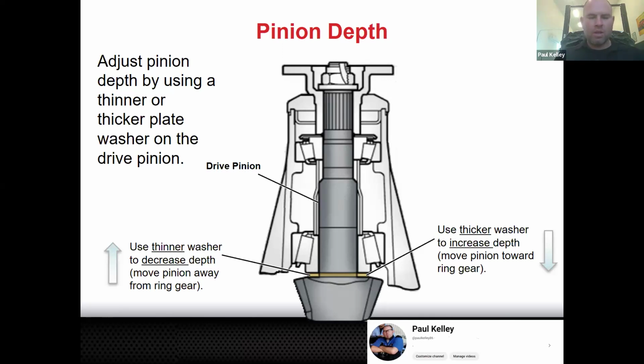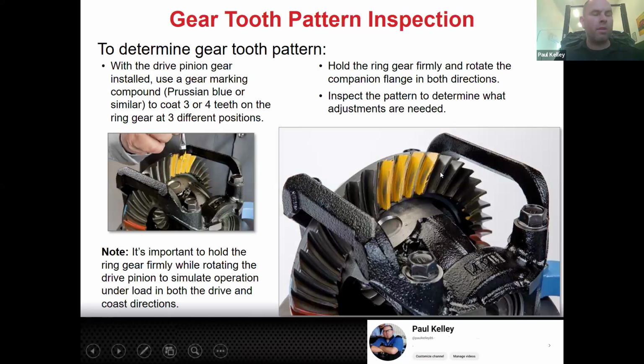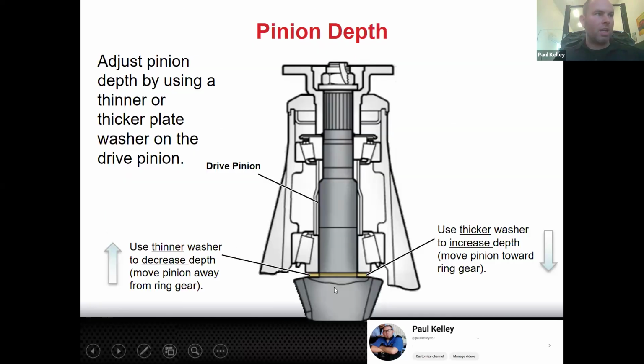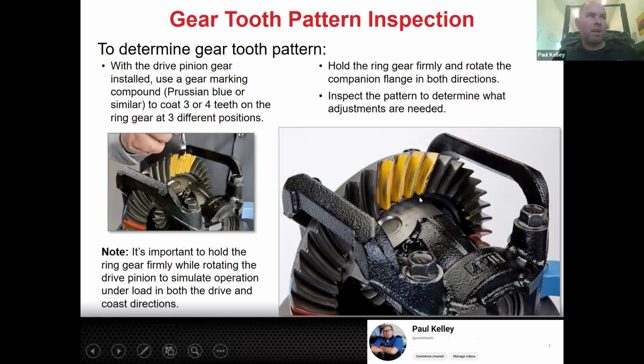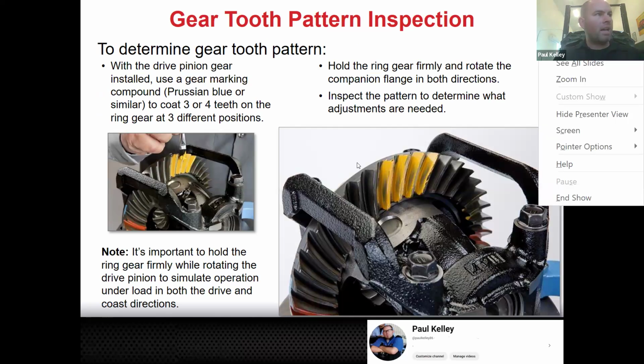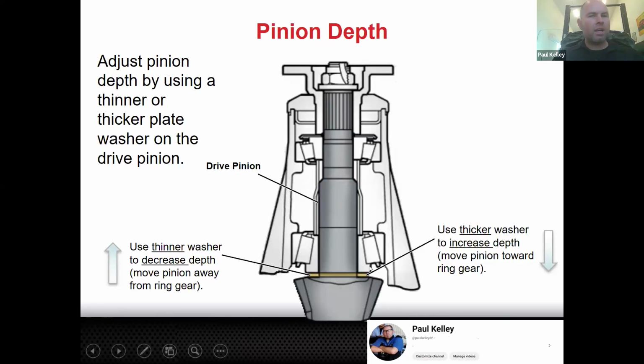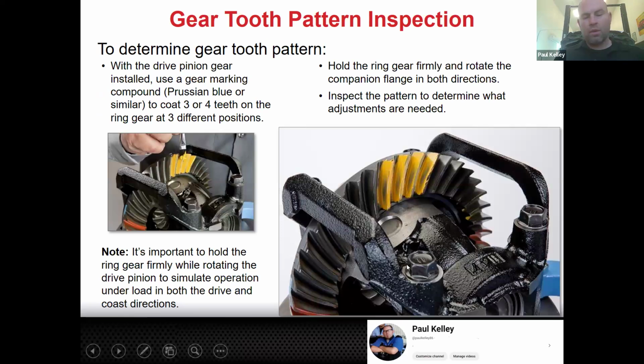Because if you put your setup bearings in and your pattern is off, you may have to back it up and change this shim and then put it together again. Your pattern's still off, and back it up and change this shim again, right? And you need an assortment. That's what I'm saying, it's kind of a mess. And to go from installing this shim to this, you've got to set the whole differential up just to get this pattern check.